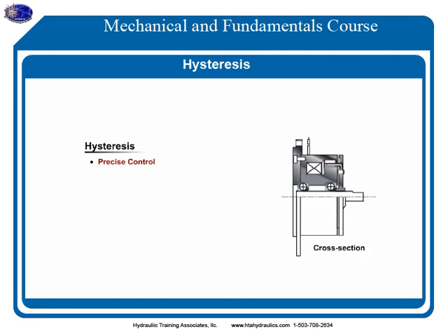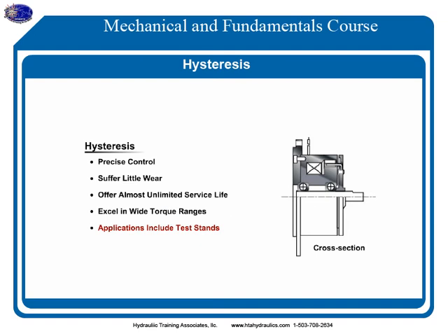Hysteresis brakes have precise control, suffer very little wear, and offer almost unlimited service life. They excel in wide torque ranges. Applications would mostly include test stands.